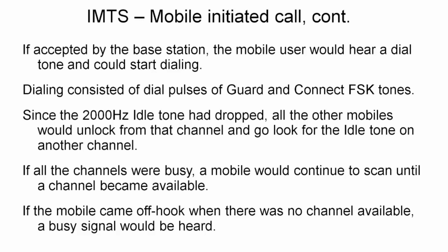Since the 2000 hertz idle tone had dropped, all the other mobiles would unlock from that channel and go look for the idle tone on another one. If all channels were busy, a mobile would continue to scan until it found a 2000 hertz idle tone. If a mobile came off hook when there were no channels available, a busy signal would be heard.